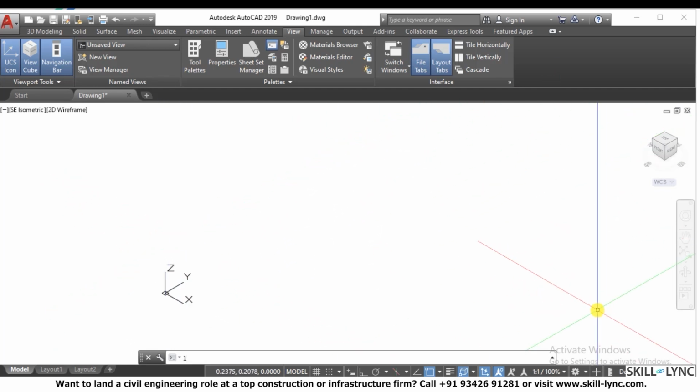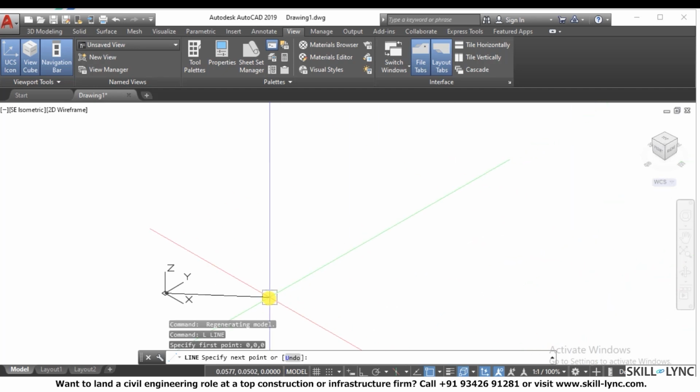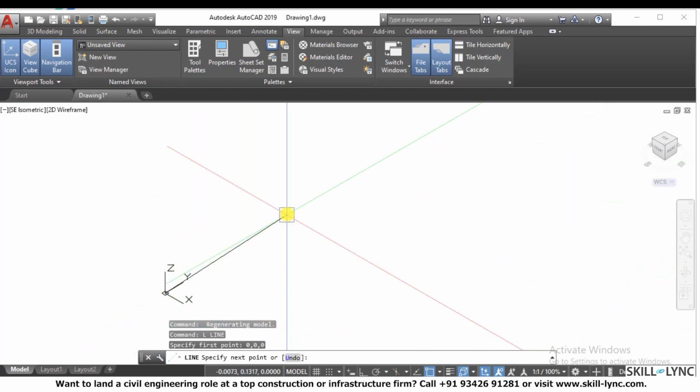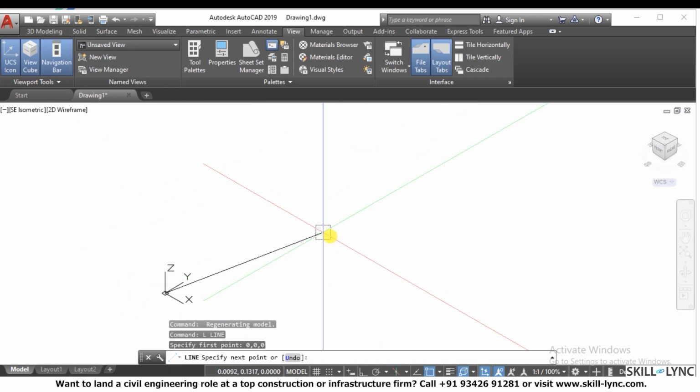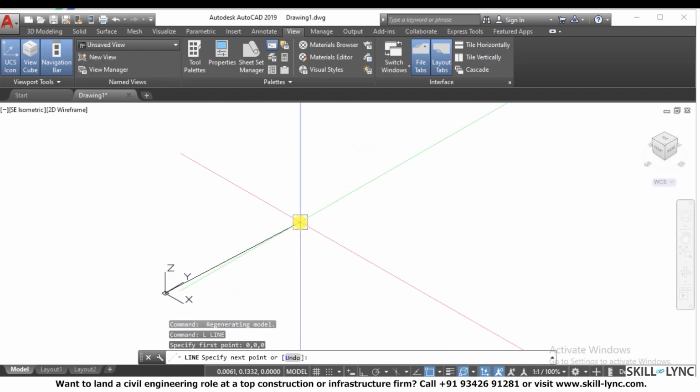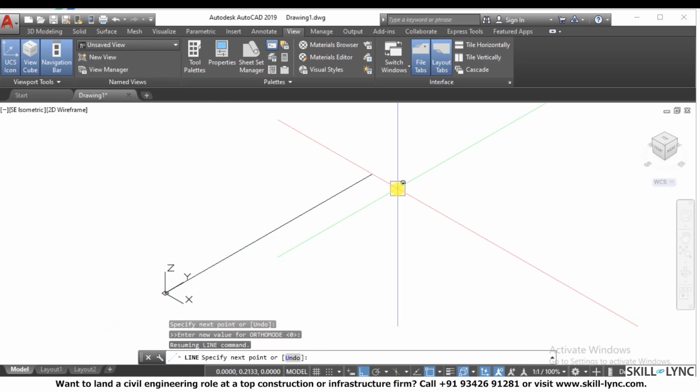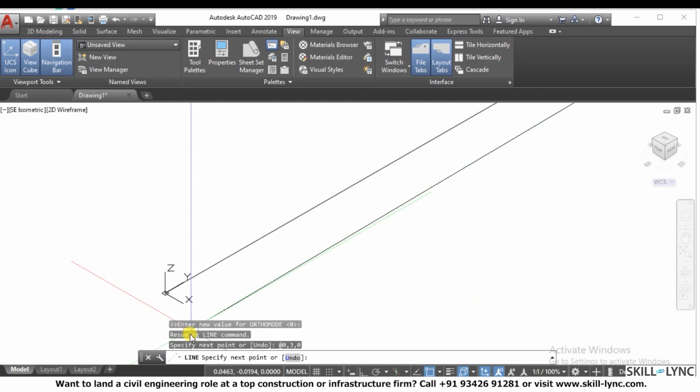The line will start at 0, 0, 0. First of all, I want to create the face in the YZ plane, so I have to go in the Y axis first. I'll say @0 in X, 3 in Y, 0 in Z. Which coordinate system have I used?